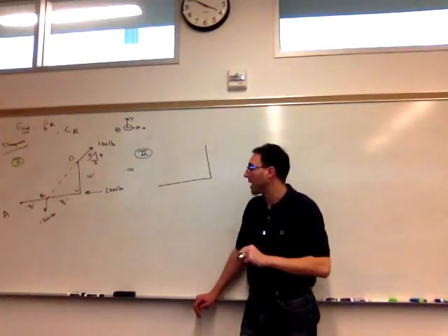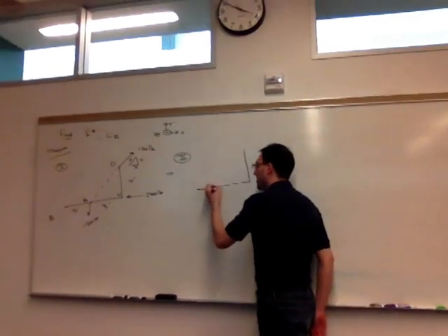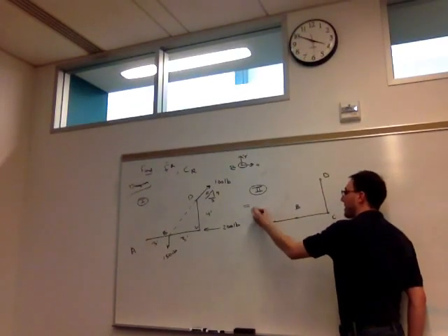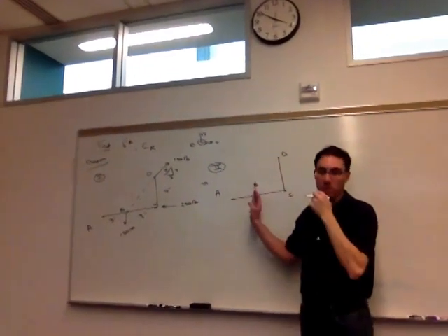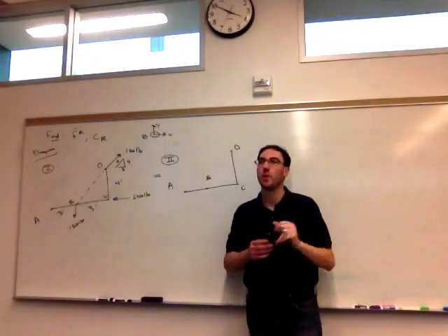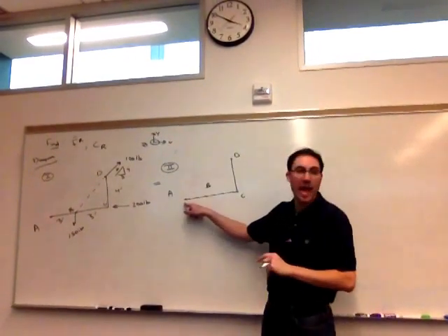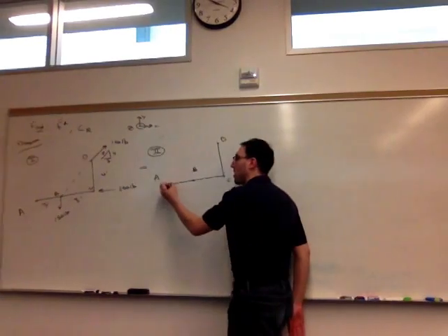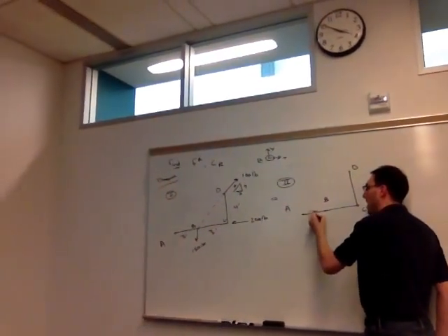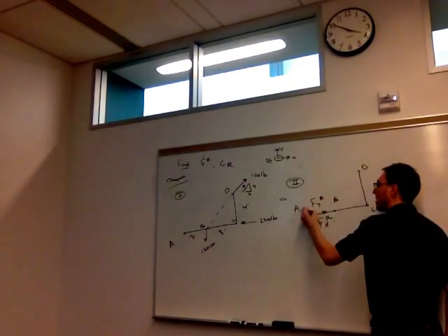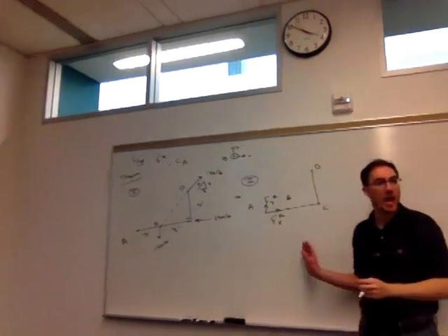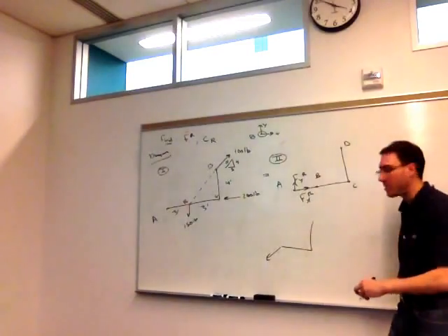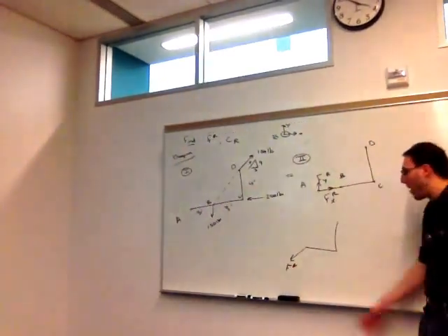Okay, so all I did was copy it exactly with those 3 forces. So I have that same bracket in my second system. However, here, this is my simplified version. What I'm looking for is an equivalent system with a force and a couple acting at point A. So the force, as I said in the previous slide, I'm going to jump right away into writing in component form. So Fxr and Fyr. I'm going to assume it's positive, and then at the end, see if I'm right or wrong. In reality, the force is going to be just some magnitude and direction, Fr. But I'll get to this.